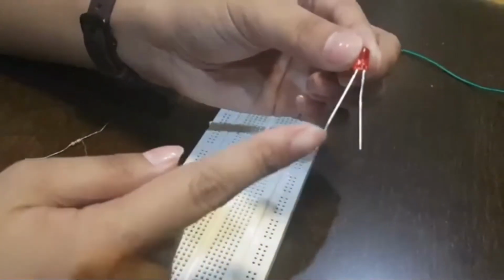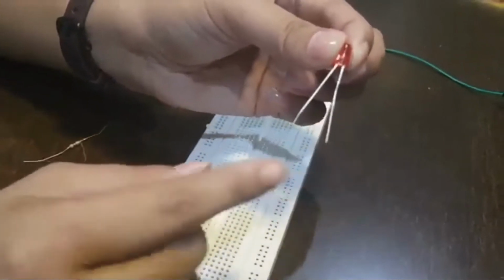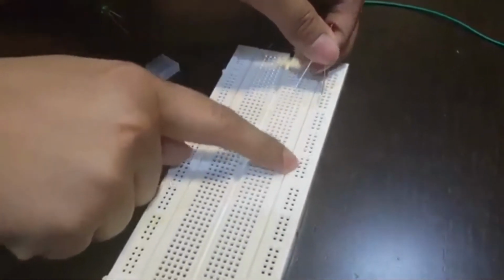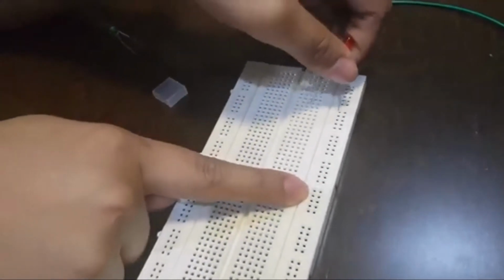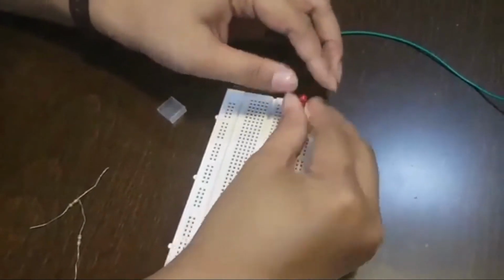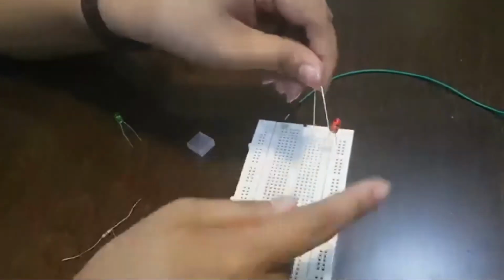The breadboard provides temporary connection between some electronic elements. So, we connected the shorter leg of the LEDs to the horizontal connected holes. This way, all the short legs, which is the negative side, is connected to the single node. We place enough distance between the LEDs so as not to overcrowd.